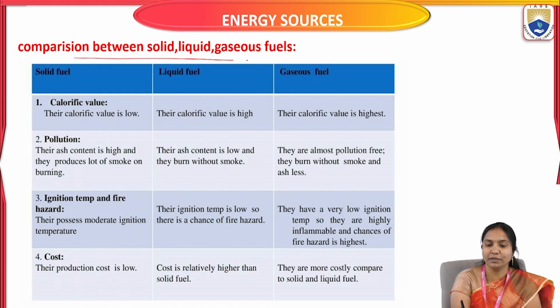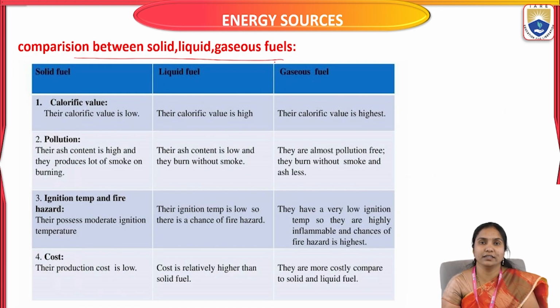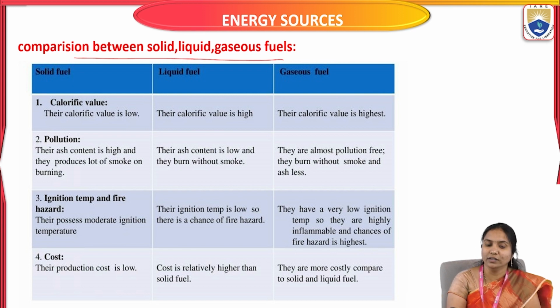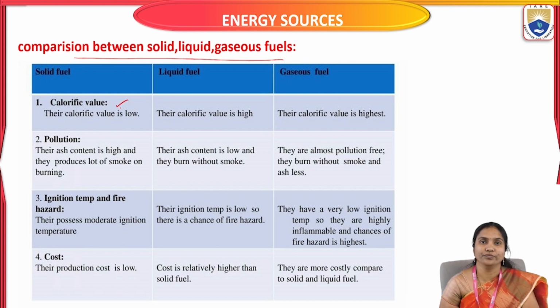Now let's discuss the comparison between solid, liquid and gaseous fuels. First we discuss calorific value. Generally, fuels are classified into two types, as we already discussed: primary fuels and secondary fuels. Based on physical state, these fuels are again subclassified into three types: solid fuels, liquid fuels and gaseous fuels. How can we compare them? The first one is based on calorific value.